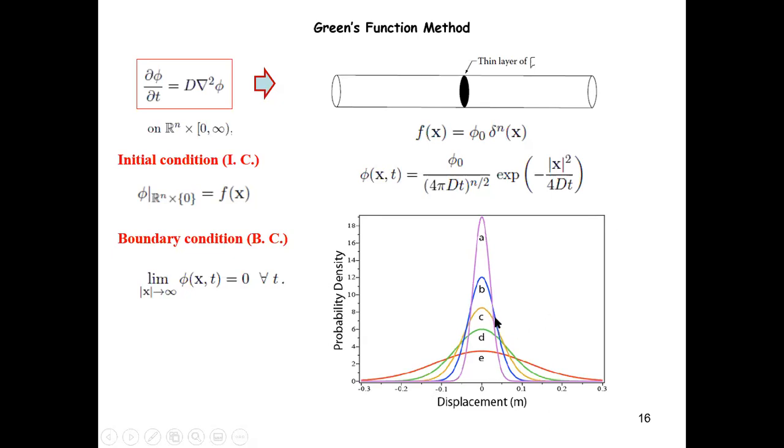If you wait a little bit longer, you see a further decay of the concentration within this middle region, and then the carbons diffuse further and further. Eventually, the red line is the later time, where you have a relatively smooth distribution of carbon. Of course, when t goes to infinity, the carbon is going to be uniformly distributed within the bar.